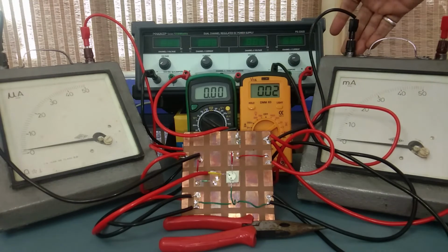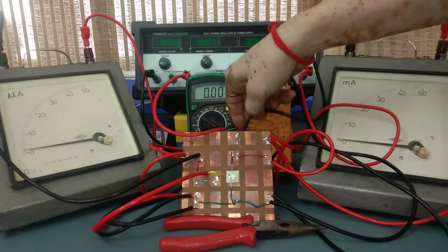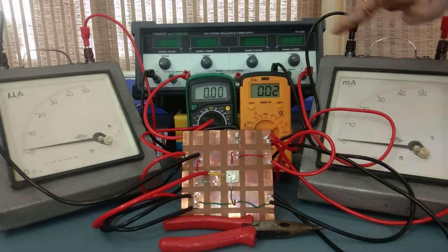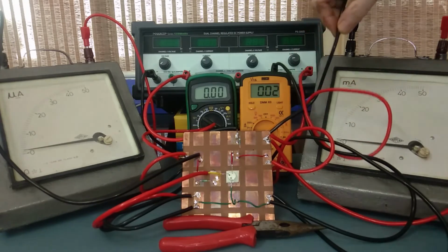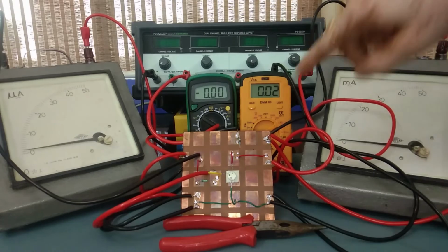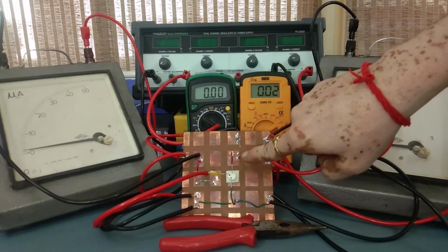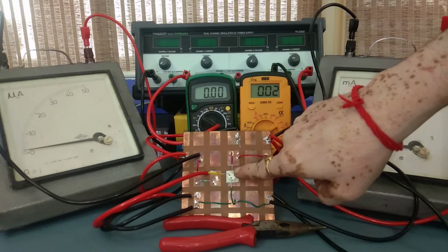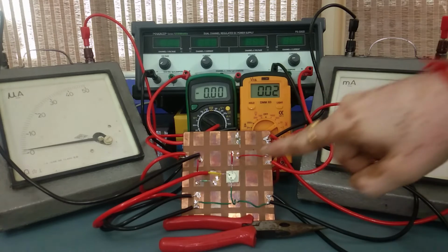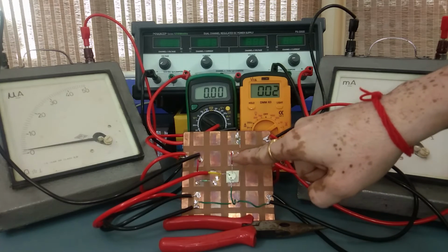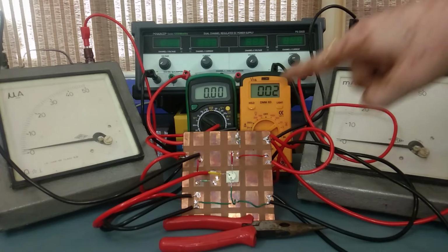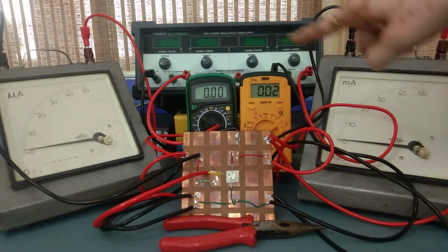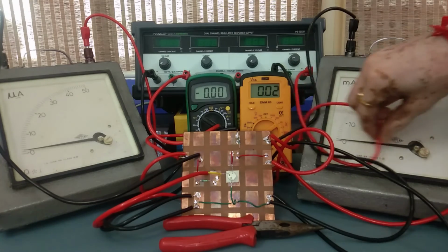Now you see the negative terminal of the current meter has gone to this point. This wire has gone to this point. It's a bit clumsy. Here the collector resistance is there, and after this collector resistance there is the collector terminal. So you can find that the collector is connected to the source through this resistance and this ammeter. So we can read the collector current, and the collector current is limited by this resistance. So it is safe.